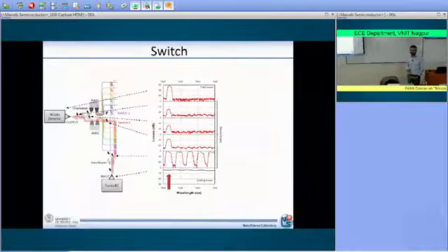What can you say of this result? Any comments here? Is the switching working or not? Yes, it is working. We want to send this blue light there, and indeed we are able to send this blue light there. But here there is an issue. What is the issue? Look at the number here. Yes, power losses, minus 20 dB. It means that we are losing 20 dB of the input optical power. That is huge. But let's see if we can work on another channel.